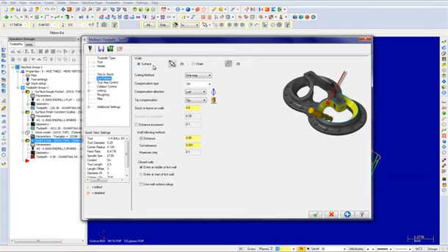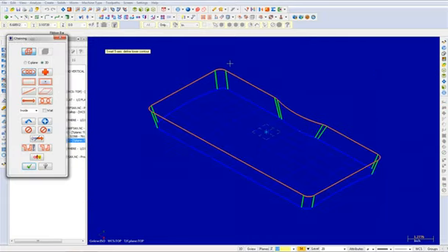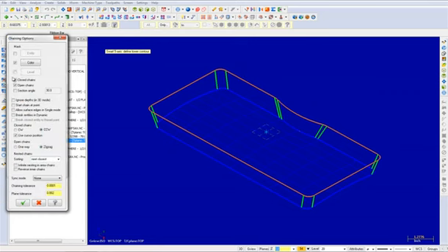The Walls area allows you to select the wall surfaces using the surface selection or by selecting the upper and lower rails created as geometry using the chain selection. Enable Chain, then click on the Select button to the right of it. Enable 3D, then select the Options button. Disable the color mask if needed, and change the sync mode to by branch.